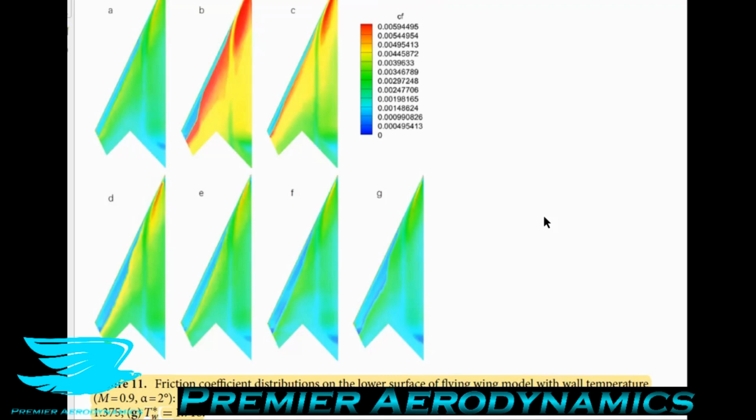It not only affects where the transition occurs, it also affects the friction coefficient after you've transitioned, which makes sense to some extent. The energy of the flow is still being affected by the wall temperature. It's just that we often don't think about the effects of the wall temperature after transition, because we often just want to know where the transition point is and how that is affected by the wall temperature, at least.